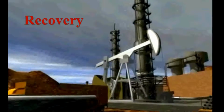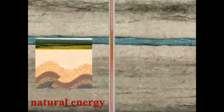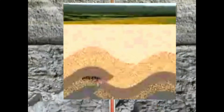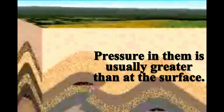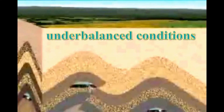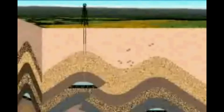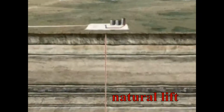Recovery, involved in the initial production stages of many newly producing wells, relies, for the most part, on the natural energy present inside the reservoir that was trapped there along with the hydrocarbon molecules as the reservoir was being created. In these newly trapped reservoirs, the pressure inside them is usually greater than at the surface, in what is known as underbalanced conditions. When the reservoir is uncapped in underbalanced conditions, a pressure differential from that inside the reservoir to that at the surface causes the trapped energy along with the hydrocarbons to be pushed to the surface in what is known as natural lift.